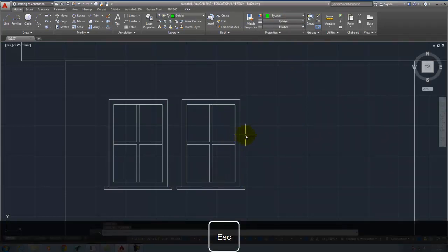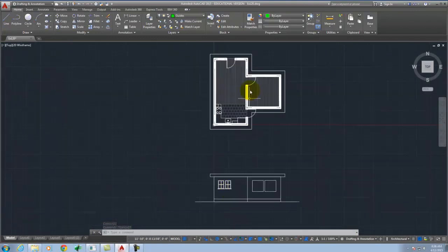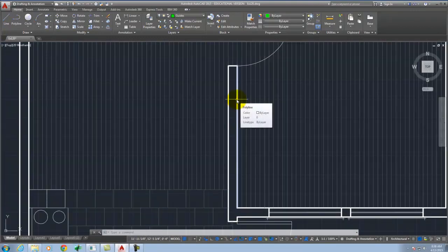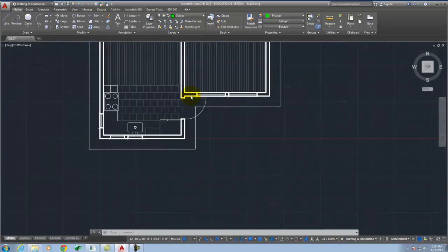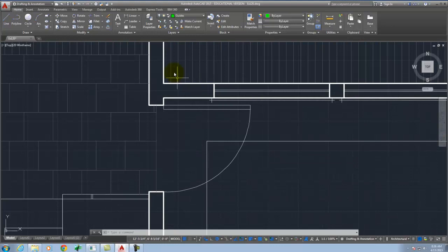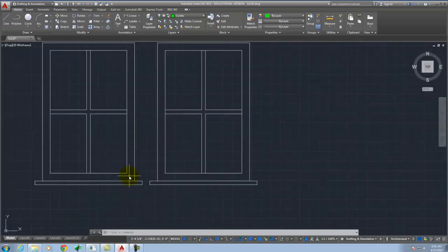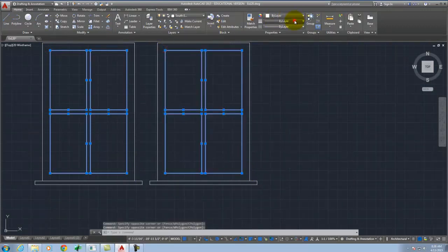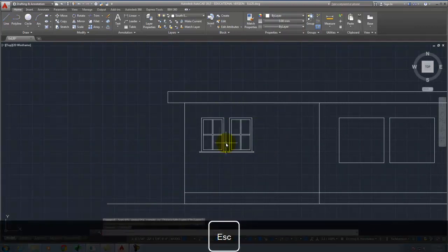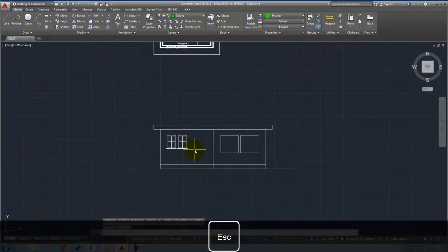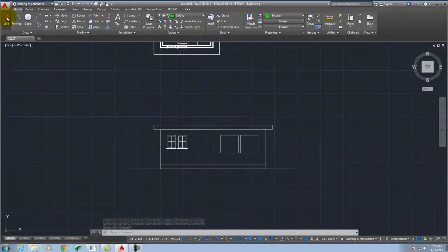One of the things about display mode in AutoCAD is it's very hard to see thinner line weights. So you need to be at 0.25 or more to see it on screen, but when you print it, it'll end up being thicker. Okay? So if we're looking at the lines that I've drawn, we're not really seeing anything except for the fat lines that represent the walls themselves. So anyway, we could come in and continue. We could make the interiors of each of these windows a little bit thinner. We could say we wanted them to be 0.00, etc. Right? So I can assign those as line weights. Okay? So we've gone through and we've drawn one rather ugly building.